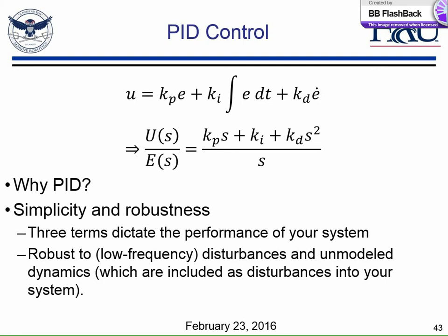All right, so of you guys that worked with a PID controller block, how would you describe it? Well, you have a proportional and integral and derivative term. Right. And by tuning those gains, the Ki, the Kp, and the Kd, you can dictate what your time response is, what your overshoot is, and what your settling time is. Yep, exactly.